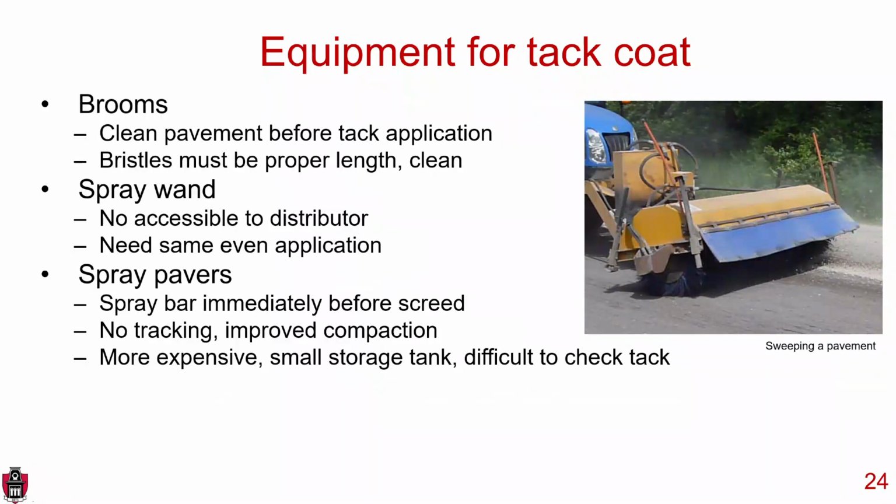There's a relatively small storage tank on the spray paver itself, so that needs to be refilled relatively frequently. And it's difficult to check the application rate and the quality of the tack because it's all in one machine. You can't just look at it and say, oh, that nozzle's out, that nozzle's clogged, because it's all hidden inside of the machine.